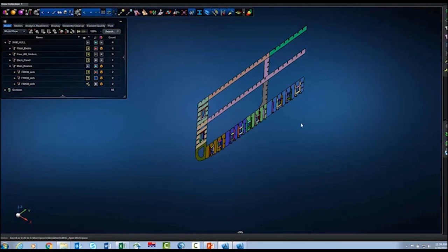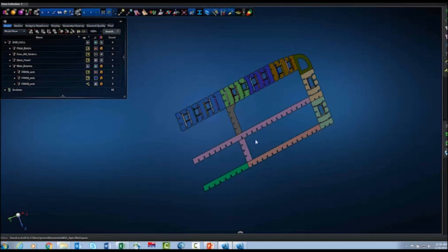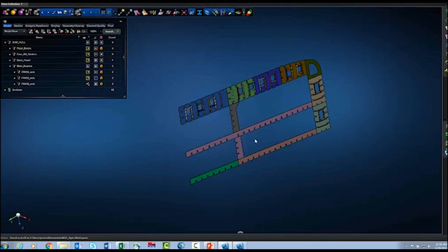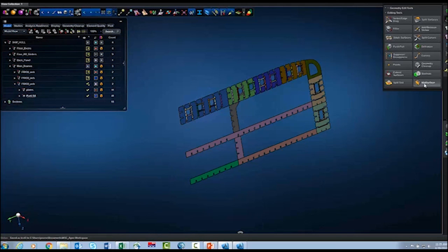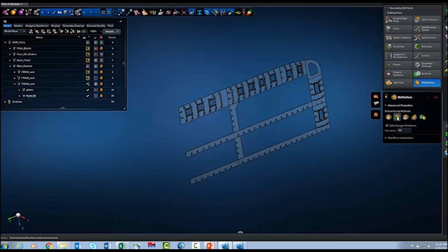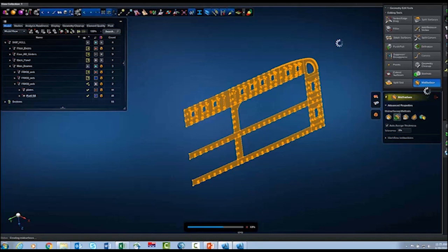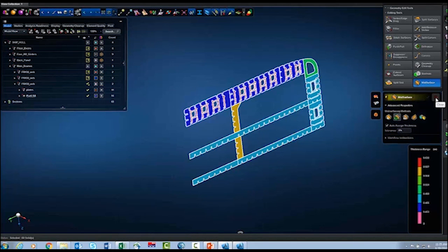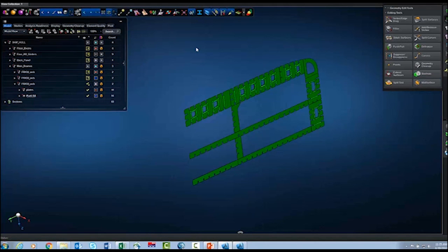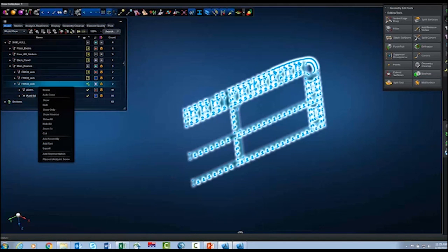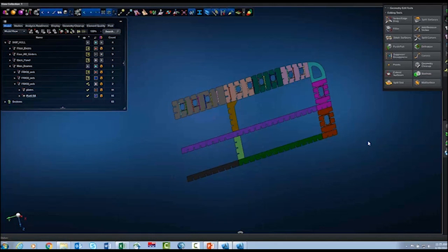And we're going to incrementally validate this particular frame. This is actually a bunch of solids. So let's first create some mid-surfaces of this, okay? We're going to do constant section mid-surfaces because this is all flat plate stock in this case. So we'll do a drag box and create a bunch of mid-surfaces very rapidly, okay? Let's actually hide the solids so we can see the surfaces, and let's actually automatically color those. I like it when they look different colors, so I can see all the individual parts that I have, and these are the mid-surfaces from those parts.